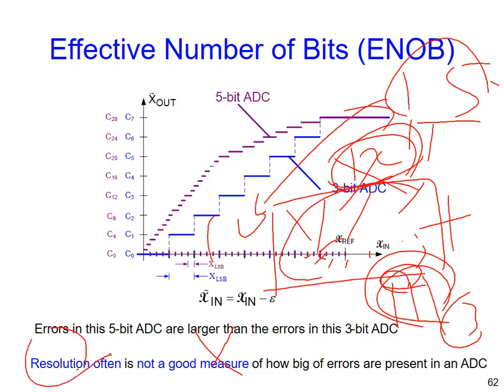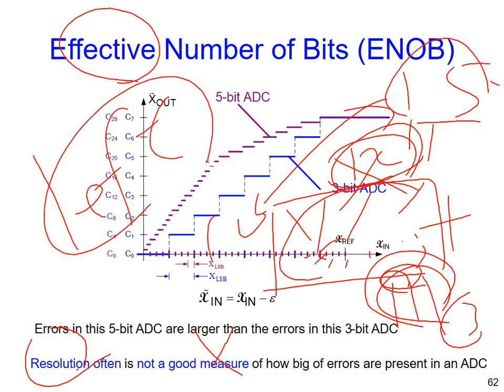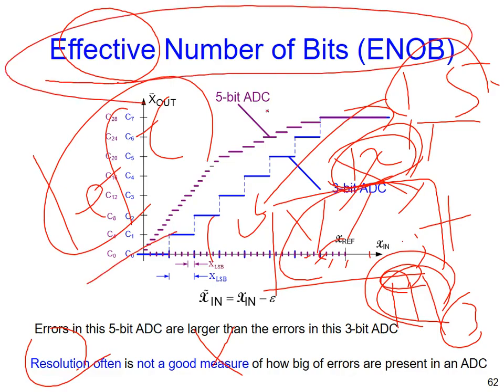Ideally, how many bits the ADC has doesn't make any sense. No. We need to focus on the effective number. After measurement, effectively, how many bits are left, right? That's it. So the price is supposed to be decided on this instead of the resolution from the beginning. After measurement, you can think, how much money would I like to pay for the chip? That is the ideal case.